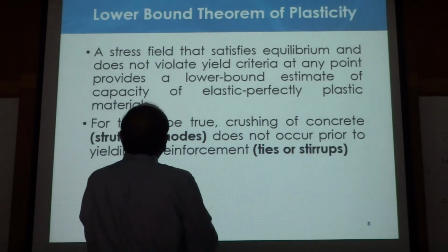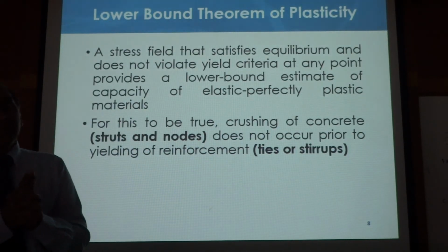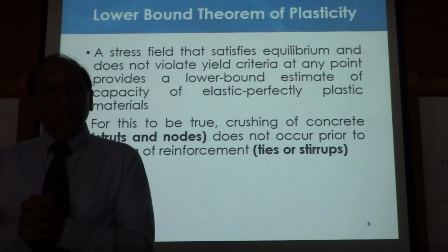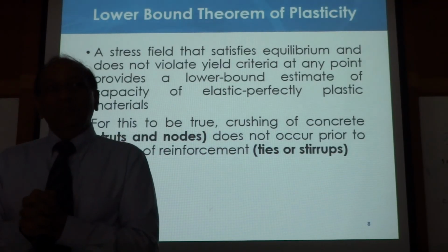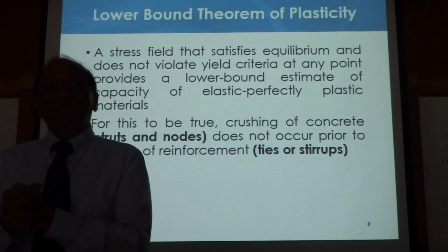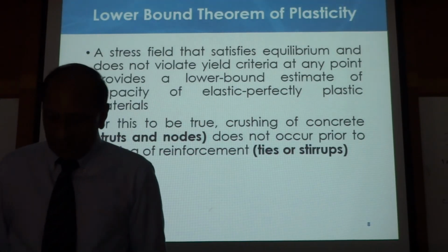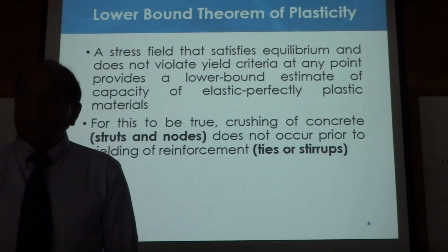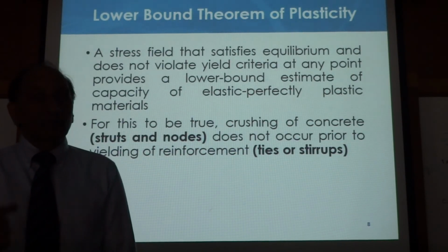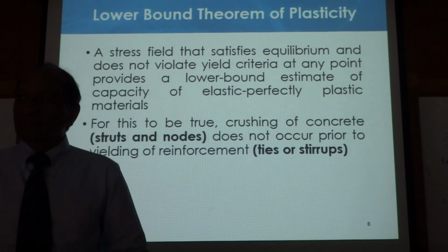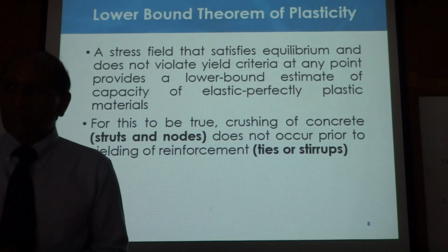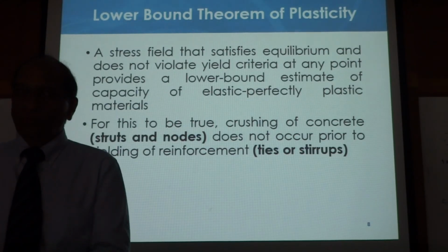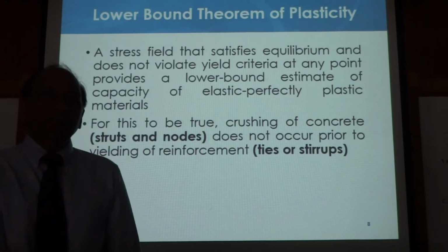But what we are saying is that this stress field that you get from plasticity gives the actual capacity of the medium. If you calculate the capacity of the soil based only on the area of your foot, you get a certain capacity, but the actual capacity will always be higher than that, because the plasticity will distribute on the sides.